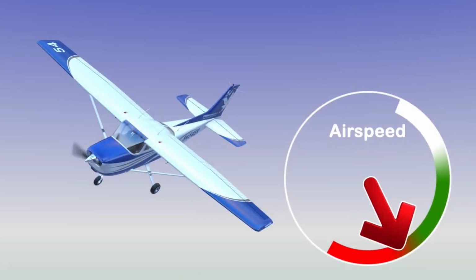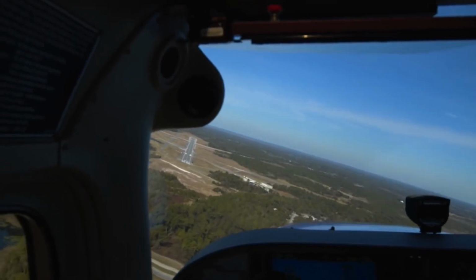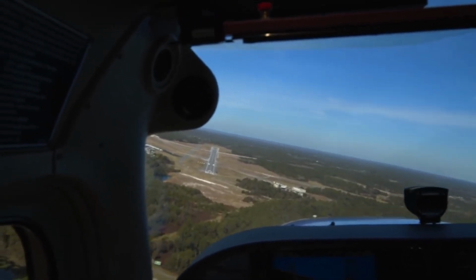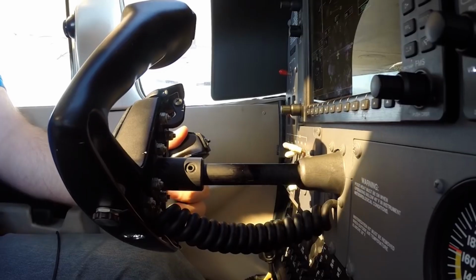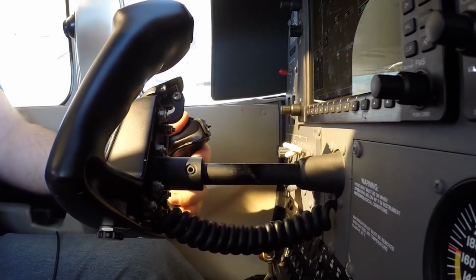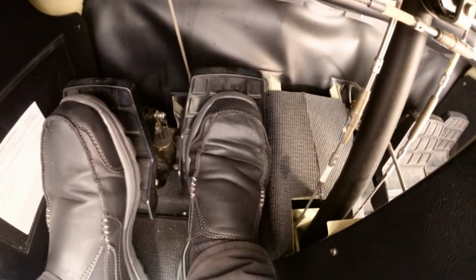Crosswind landings are a little more difficult to perform than crosswind takeoffs, mainly due to different inputs involved in maintaining accurate control of the airplane while its speed is decreasing rather than increasing as on takeoff. There are two usual methods of accomplishing a crosswind approach and landing: the crab method and the wing-low, side-slip method.